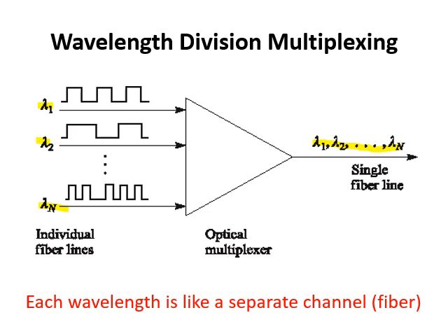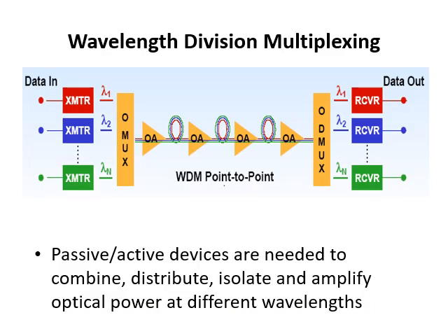So all the wavelengths in a single channel can be transmitted with the help of wavelength division multiplexing. This is one more diagram, consisting of many multiplexing and demultiplexing units. As you can see, on the input side, n different wavelengths are multiplexed and put into the channel over a long distance, with many amplifiers used in between to amplify the data. For long distances, there should be amplifiers.